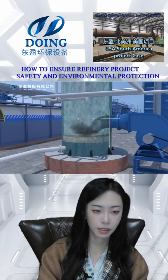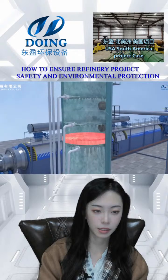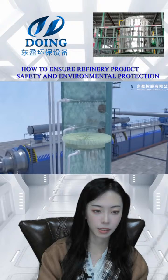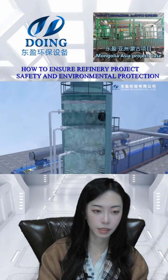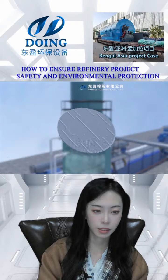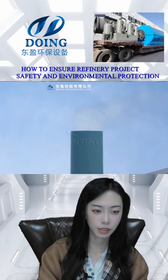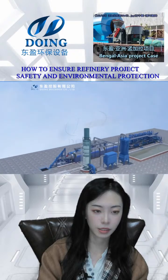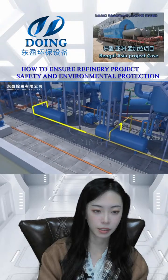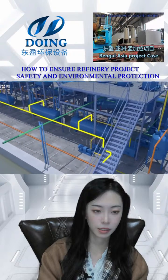They're kind of different. And the third difference is the standard of the raw material. Like the batch type pyrolysis plant, we don't need to have much pre-process. We can put in the whole tire, mixed plastic, oil sludge, or mixed coal tar oil sludge, aluminium plastic, or whatever, if they have oil inside, into the pyrolysis reactor.